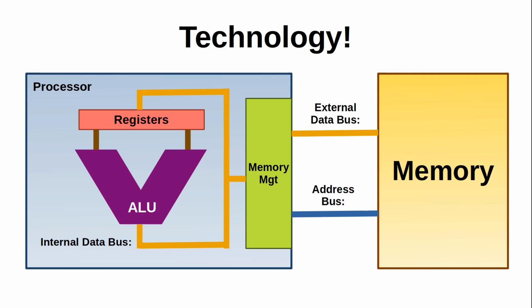So most 8-bit computers have a 16-bit wide address bus, but of course we have the understanding that a 16-bit address bus is not going to make a computer 16-bit. It's absurd. It's just not going to happen. But then we get into the actual processor itself, and the memory management component of that processor is then going to relate all of this.